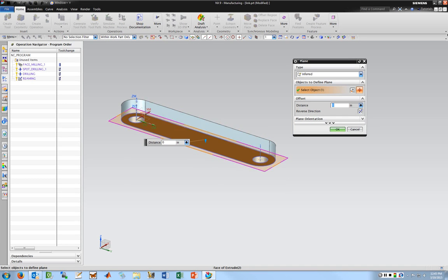Or I could leave a little bit of thickness on the bottom. If I want the best surface finish, I could actually machine down past the surface a bit, but I'd have to have a thicker stock to do that, and then I'd have to take the finished part out, stick it back in a machine, and then face mill it flat if I wanted it to be nice. So let's just assume I just want something. Basically, I just want to get it done.